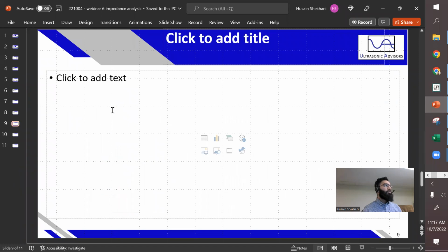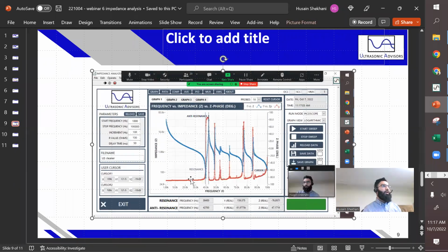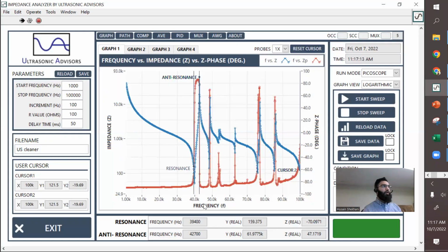I think we may only get through this transducer, but that's cool. So this is the response. The resonance frequency is at 40 kilohertz, and I'll just zoom into that area. If you have questions as I'm going, just curiosities as to why there are so many modes, or why there are no modes under this frequency, like this seems clean. Why is that? Or just clean or non-eventful.